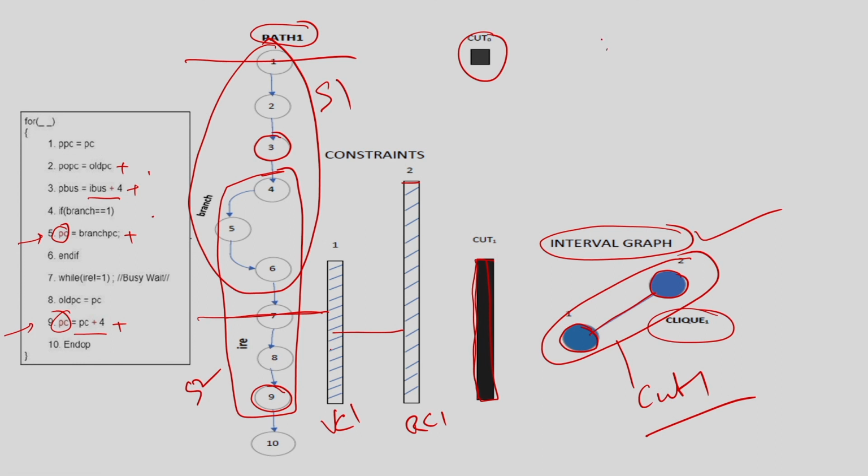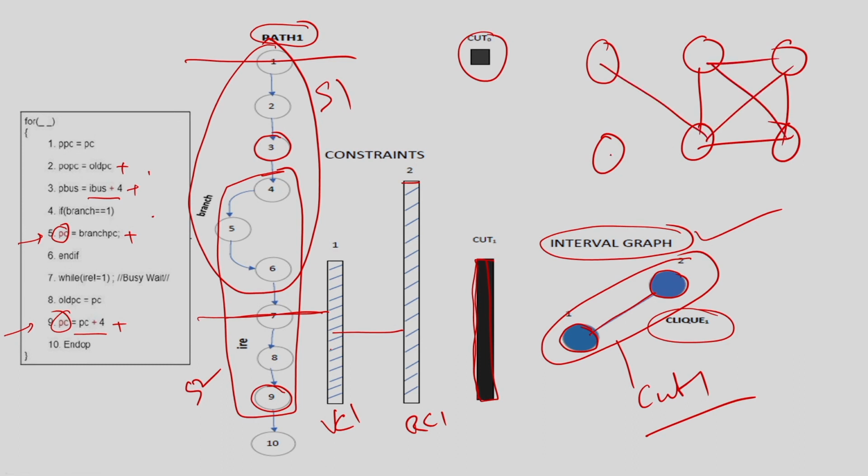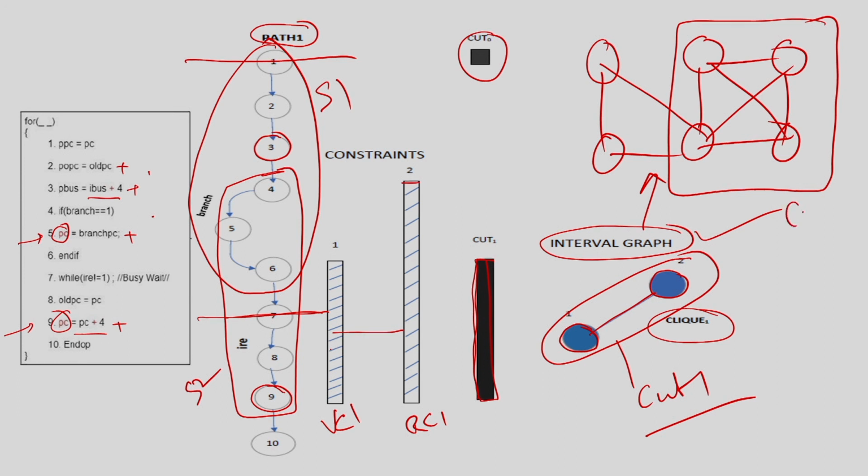Okay. Now, let us take a more complex example, where my constraint graph, the interval graph, becomes like this. Now you see here I identify a complete subgraph. This is one complete subgraph and in this subgraph I have 4 nodes. So, you can have only one cart, cart 1, which will satisfy all these 4 constraints because they are all compatible with each other.